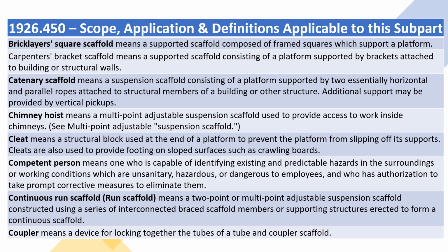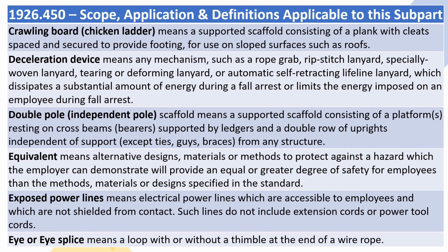Continuous run scaffold means a two-point or multi-point adjustable suspension scaffold constructed using a series of interconnected braced scaffold members or supporting structures erected to form a continuous scaffold. Coupler means a device for locking together the tubes of a tube and coupler scaffold. Crawling board, chicken ladder, means a supported scaffold consisting of a plank with cleats spaced and secured to provide footing, for use on sloped surfaces such as roofs.